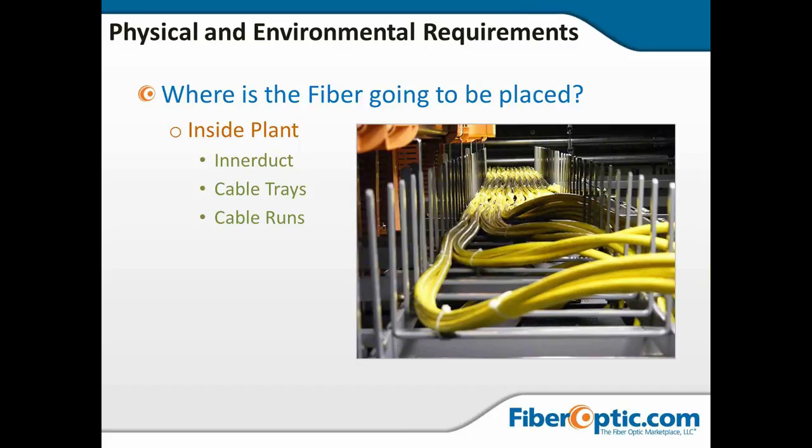If we've got a lot of fiber already installed on the bottom, and we lay more on top, then we want to remove the old stuff. How easy is that going to be with whatever route you choose? If you pull it through interduct and then you want to take out the legacy fiber and get it out of the way and run the new plant, well, you're going to have more problems than, say, if you use a tray or trough like this in the drawing. So all of these have to be weighed against the future. We always have to plan for the future.